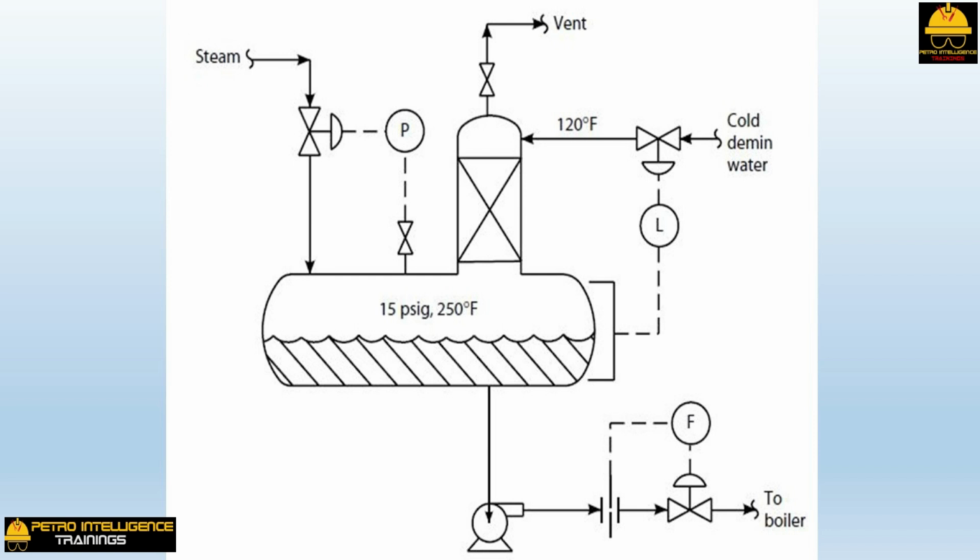Someone had the latter problem at the refinery. The refinery was spending a small fortune on the oxygen scavenger chemical, pyridine. All the engineer did was lower the deaerator set point pressure from 18 to 13 psig, and the residual oxygen in the effluent BFW dropped by an order of magnitude.